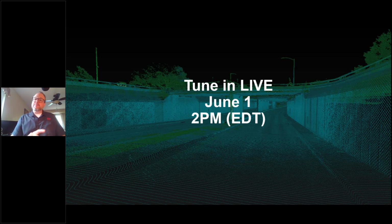And the more you can look at and the more you can understand each one of those plots, the higher your confidence is going to be when you have to do a deep dive into trajectory quality in Inertial Explorer. That said, in Pegasus Manager, when we use NavPrep, which is Inertial Explorer Lite, we can think of it that way. When we run NavPrep, we're generating a shapefile called the QF shapefile, quality factor shapefile, and that's generated in your mission, and it's saved in the GPS INS folder of your mission.